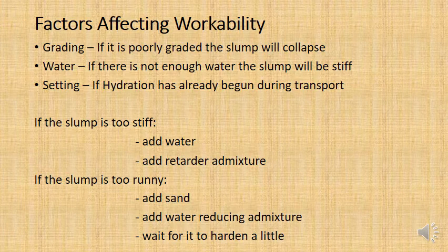So if you mix a concrete at a concrete factory and you do a slump test of it at the concrete factory and the slump is 15-20 centimeters, you could then put the concrete in a concrete truck, and by the time the concrete has arrived at the site on the other side of town, you do another slump test, and now the slump is only 10 centimeters.